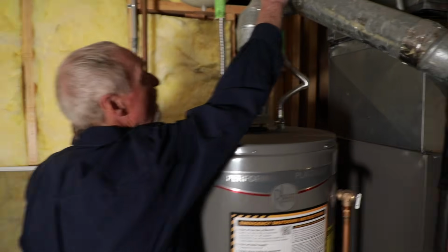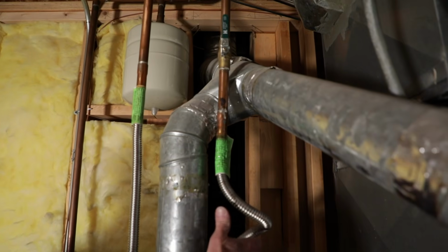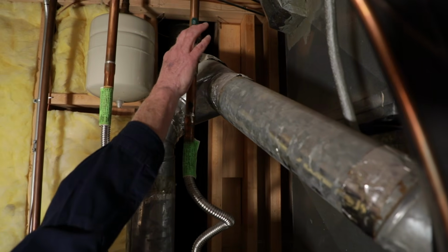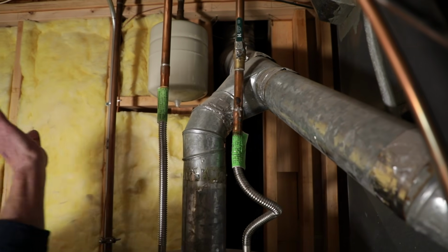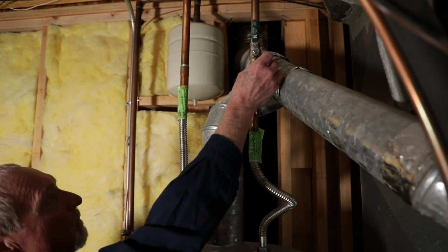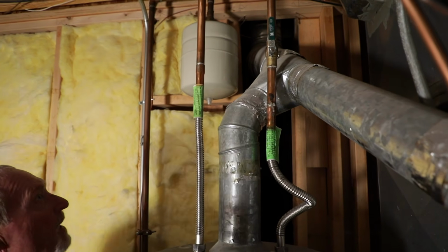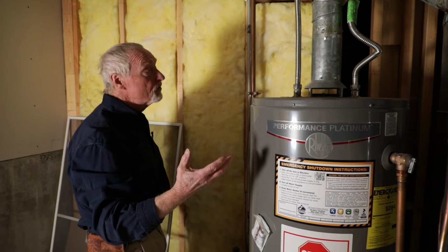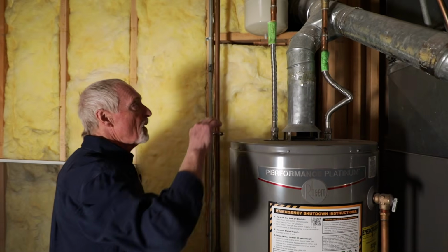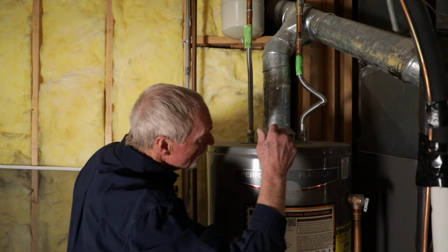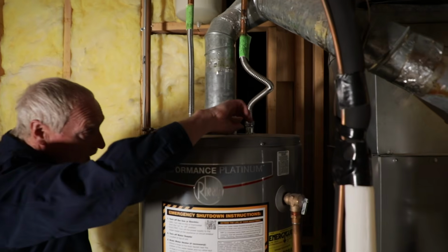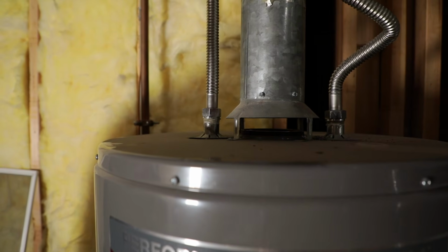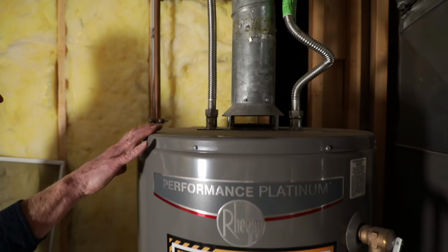So here we have our main water line, cold line, coming into the water heater. We have a valve on it, have a little bit of green up here, which is nothing, that's normal. Sometimes we'll see mineral deposits around these that are dry, indication that maybe there was some past leak, but they sealed themselves. Take a photo of that, make a note that there's past leakage, currently dry. And so we check our connections to our water heater. Here we have a dielectric nipple on each connection. That's looking good, no corrosion there. That's what we want to see, very good.